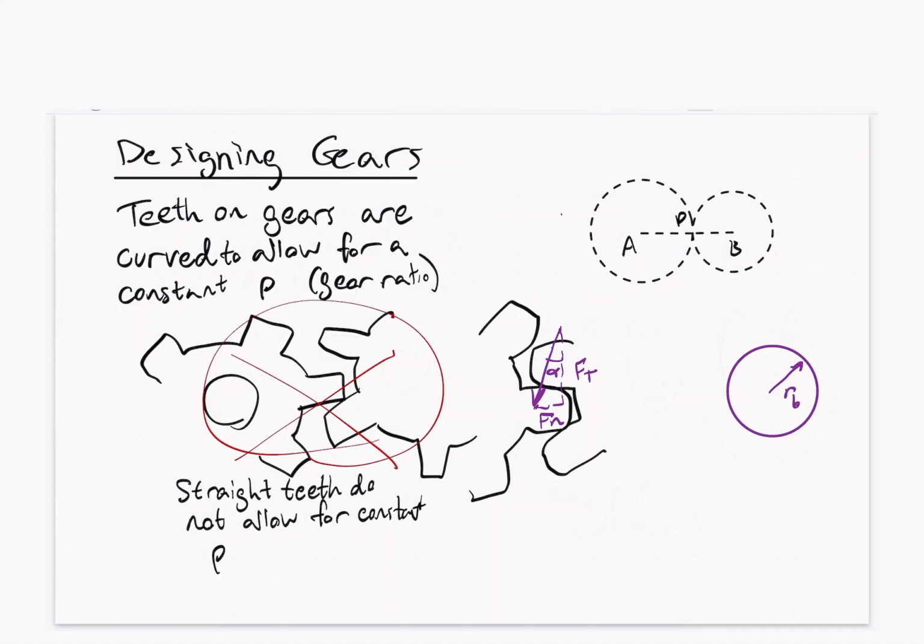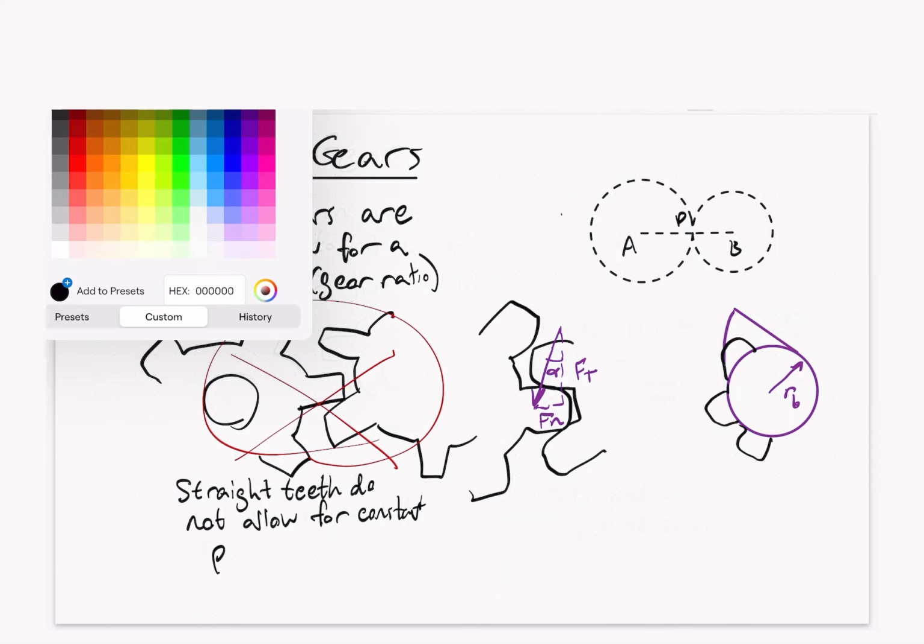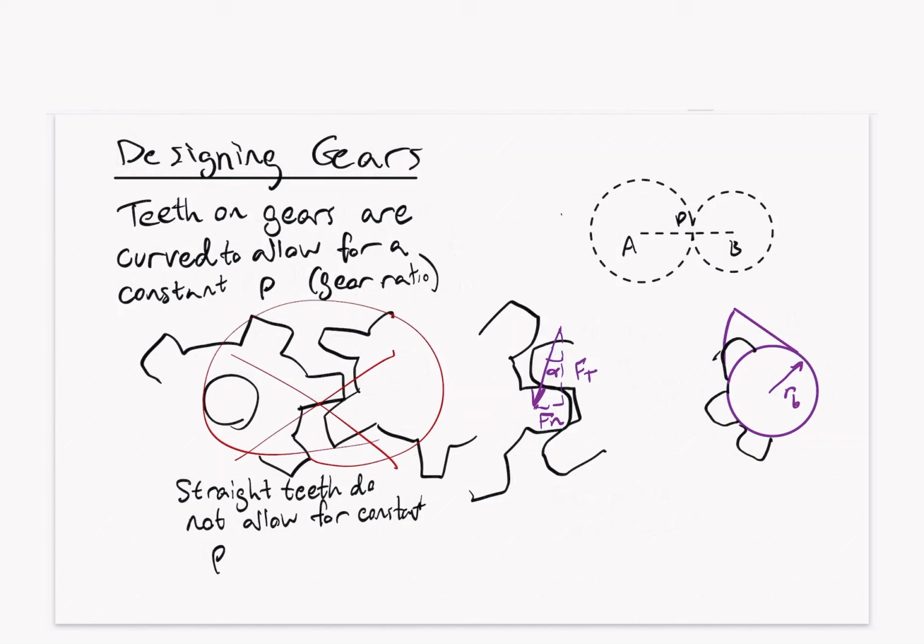And if you take a length of thread and we want to curve it around, and track the end of this thread as we pull it around our device, that path would look a little bit like this. When we draw our teeth on our gear, we're going to draw them so that they follow those paths, as if we had a string going around, and that would allow us to travel through.